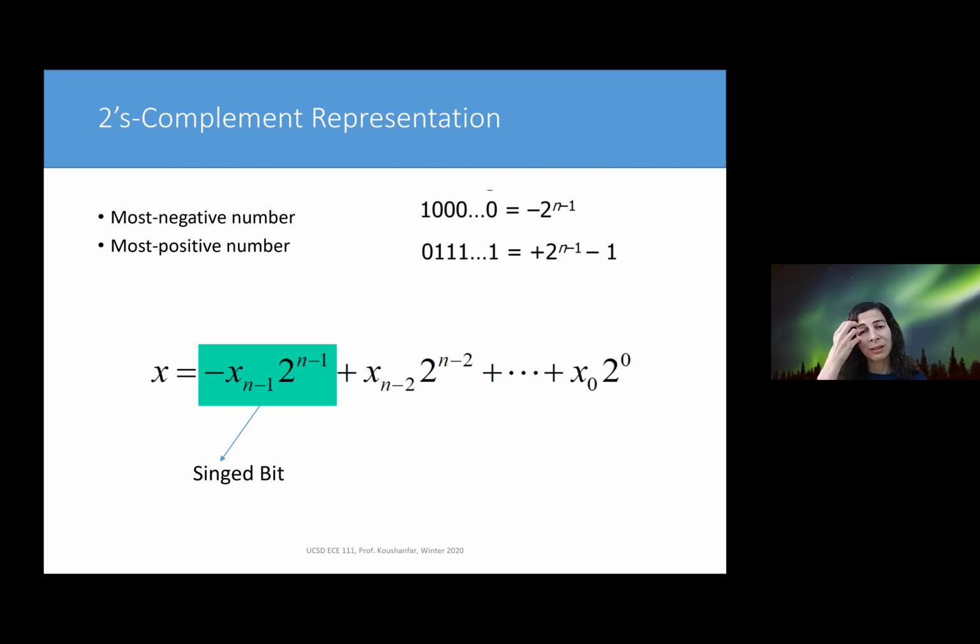So, if you want to represent, say our number is 0, 1, 1, 1, 1, 1, all the way to 1 at the beginning, like it is shown here. If you want to find its complement, we first find the inverse of this, which is 0, 0, 0, 0, 1 here, and then we add a 1 to it. So imagine that this was a 7, if you represent it in 2's complement, how you would represent it as a negative number, it would become 1, 0, 0, 1. This will become a -7.